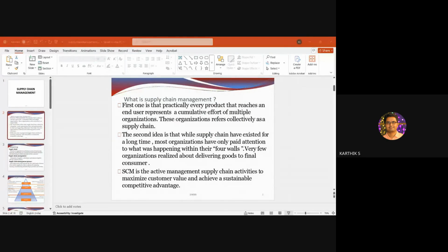Once all these departments have management people, they must have a proper flow between them. So when a material is procured and put into melting, then it passes to the molding. Then after the molding, it goes on to the knocking stage, and then it goes to cutting, gas cutting, many things like that. After cutting, it goes to shot blasting, and heat treatment processes are there, many subsequent processes to ensure that the desired material is freed from the existing mold.